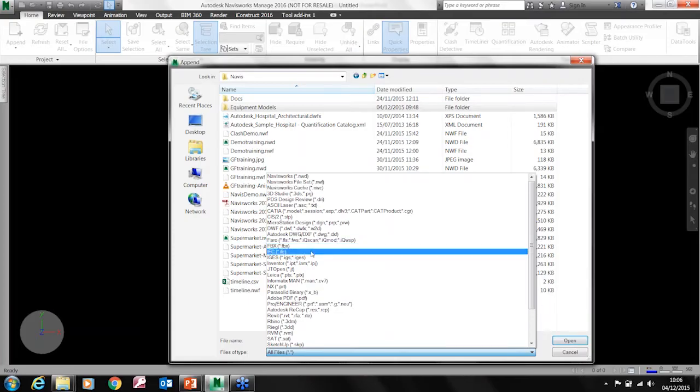And from a BIM point of view as well, it does support the importing of IFC. So if you're receiving the structural file in an IFC, or the architect's modeling in an IFC, that's Industry Foundation Class. For those of you that are not familiar with IFCs, IFCs are like the DXF of the BIM world. It's the universal language, okay? Some people might have come across it as open source BIM.